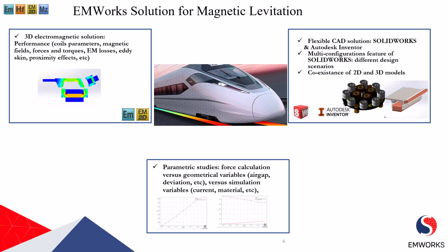also the temperature coupling, which is available for both SolidWorks and Autodesk Inventor. So you can evaluate the heat caused by different electromagnetic losses like winding losses, eddy current losses, or hysteresis losses present in the system.